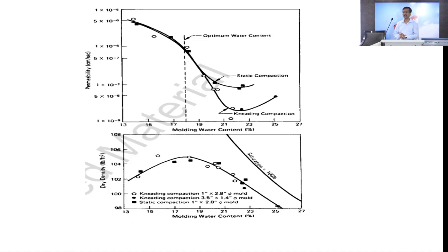The sheepsfoot roller works just like when you put your fingers into dough to knead it; if you just press it flat, that's very difficult. So this sheepsfoot, or kneading action, penetrates and gives compaction. Otherwise, in clay soil or this silty clay soil, it does not behave properly.